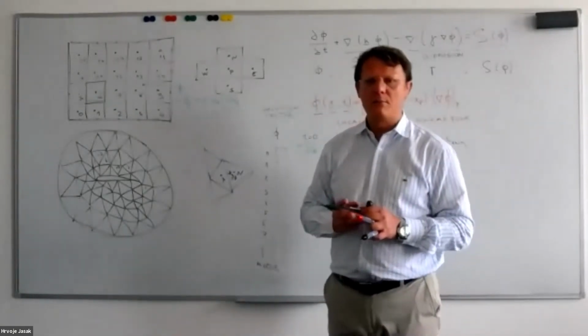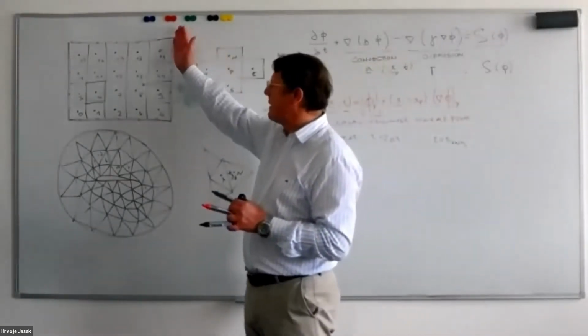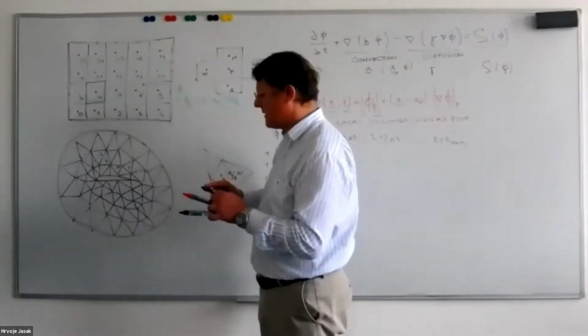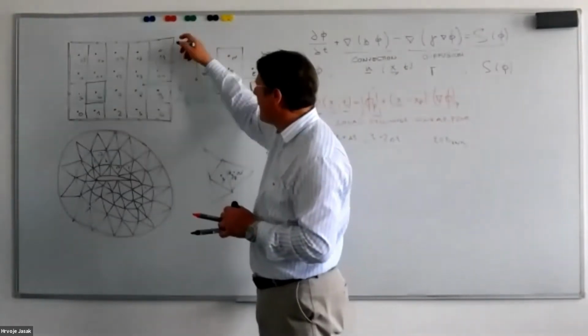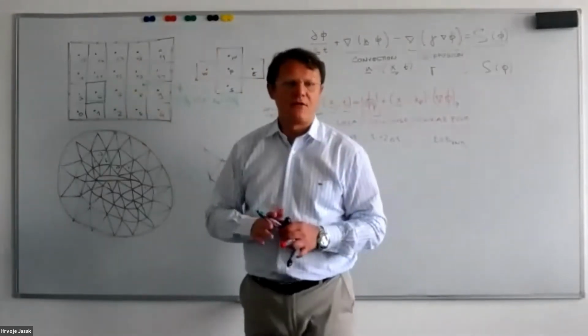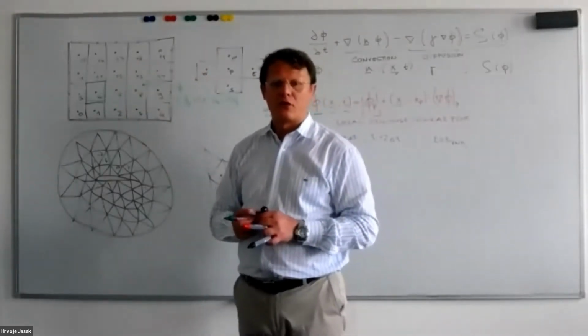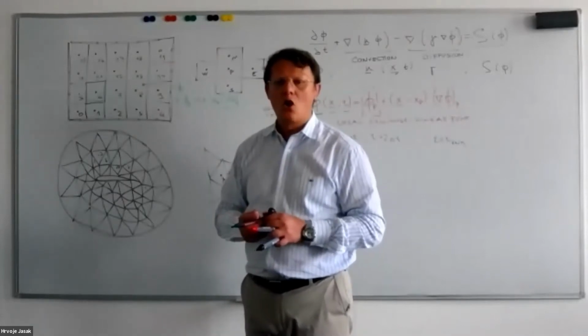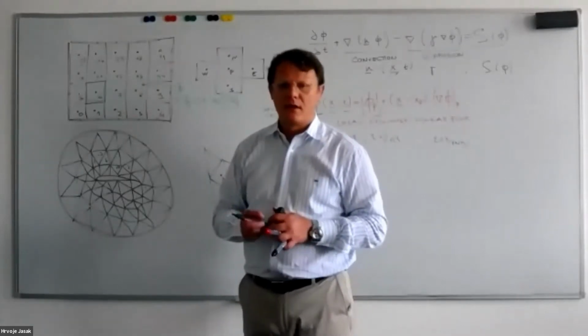I can therefore implement a Dirichlet boundary condition specifying the value of phi on all the faces of this patch, a Neumann or some other more complicated boundary conditions like symmetry planes, or indeed coupled cyclic